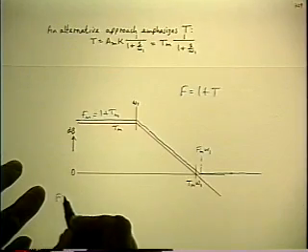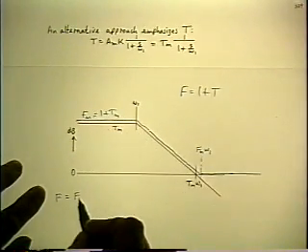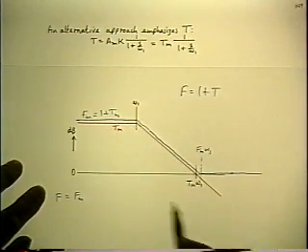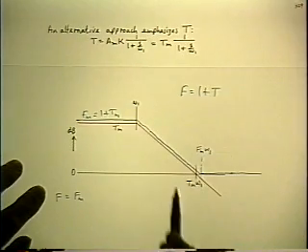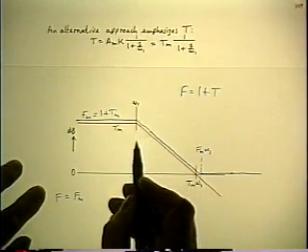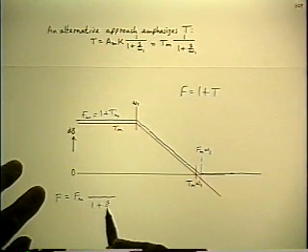So you write it, F equals the low frequency flat value, which is FM, and then you look down and you look up in frequency and see what happens. If you look down, nothing happens. If you look up, you see a concave downwards corner, which is a normal pole at omega 1.